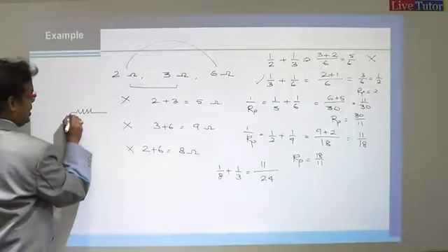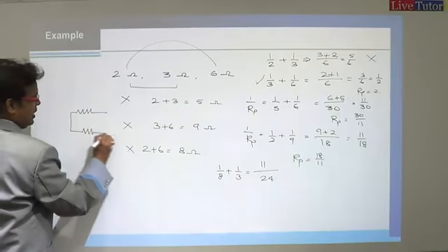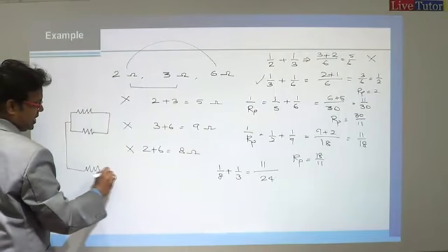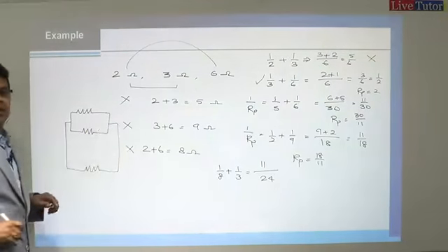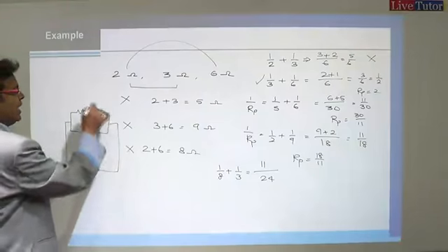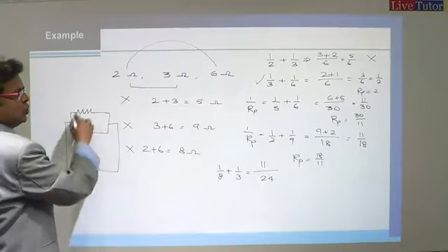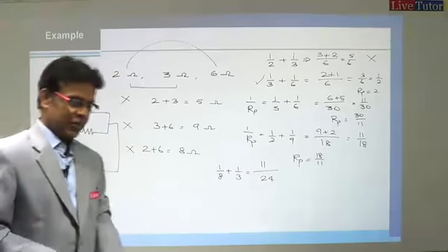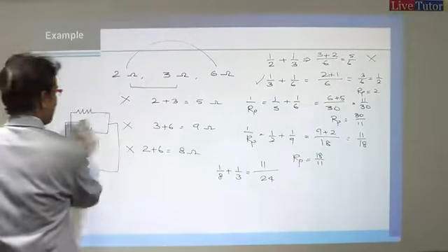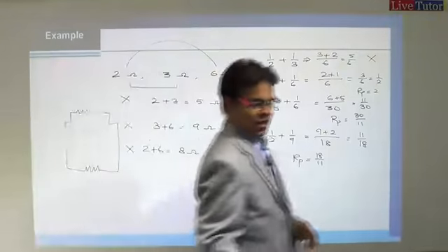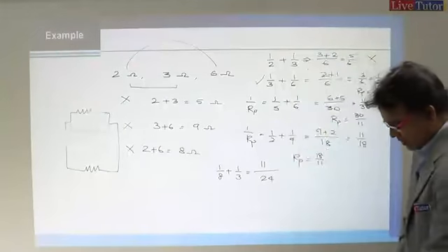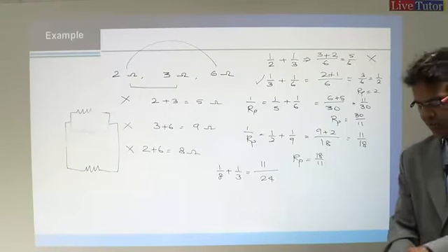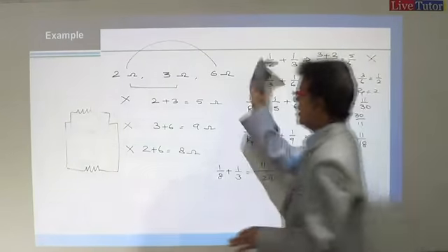This 6 ohm and 3 ohm, and this should be in series with the third resistor. So this combination will give you how much? 2 ohms. And this one is 2. So 2 plus 2 it will become 4. So this way certain problems can be attempted only by using trial and error method, as these resistances are very small, so that you can easily calculate.